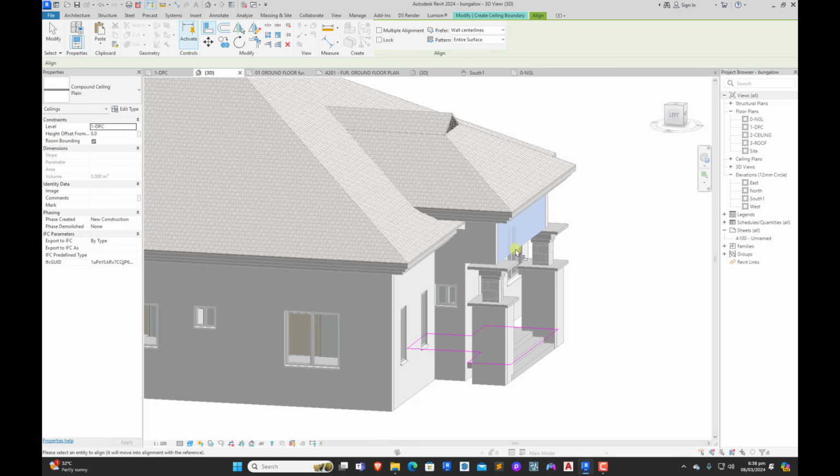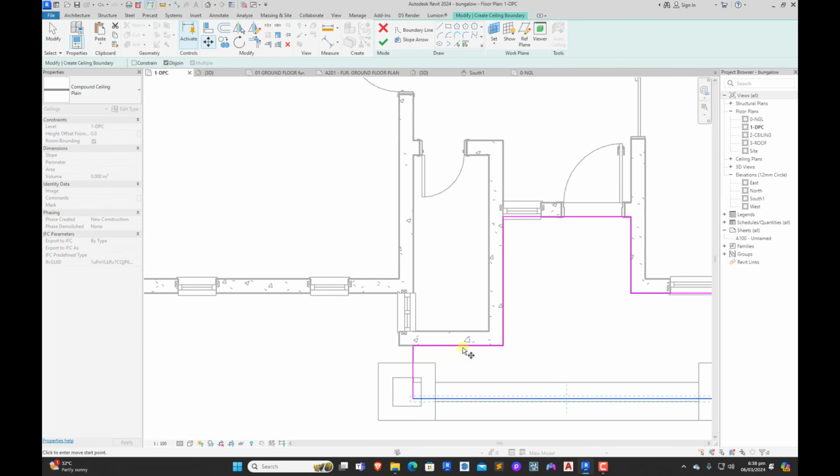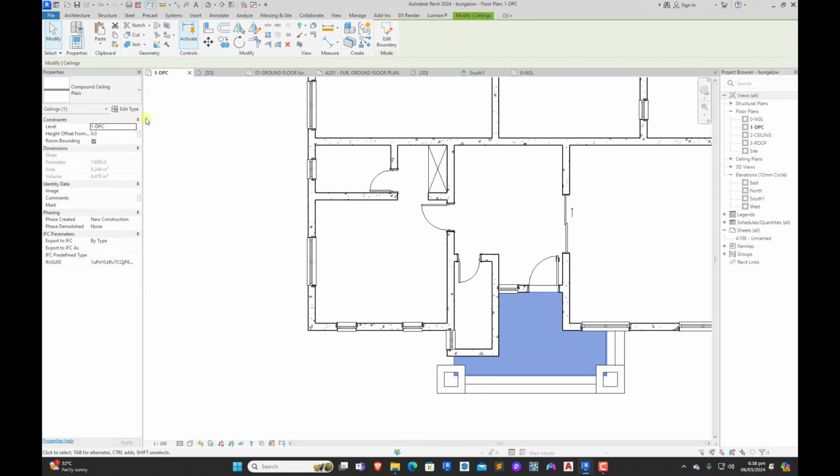Okay. So let's align this to this. So we're going to take this one in. We're going to take it in 225. Offset 225, and without copy, check copy. Good. So this is perfect. So also click on OK.